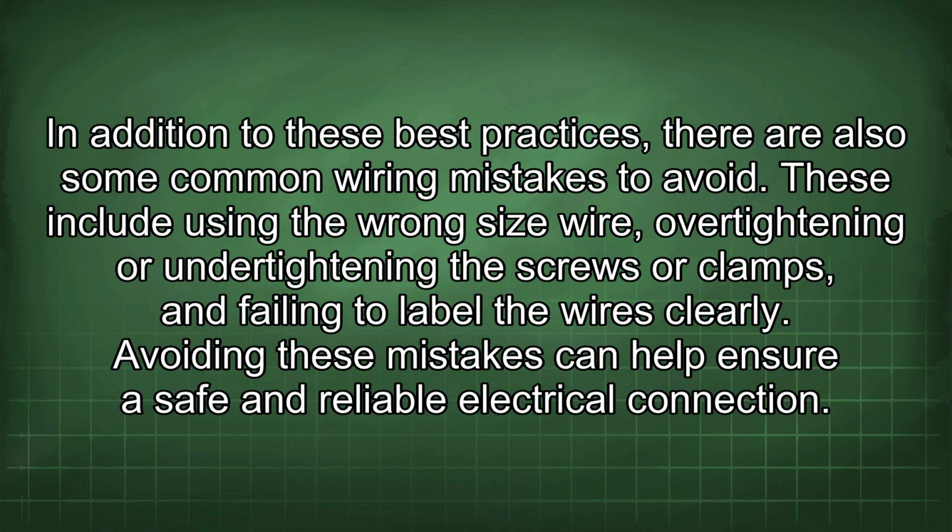In addition to these best practices, there are also some common wiring mistakes to avoid. These include using the wrong size wire, over-tightening or under-tightening the screws or clamps, and failing to label the wires clearly. Avoiding these mistakes can help ensure a safe and reliable electrical connection.